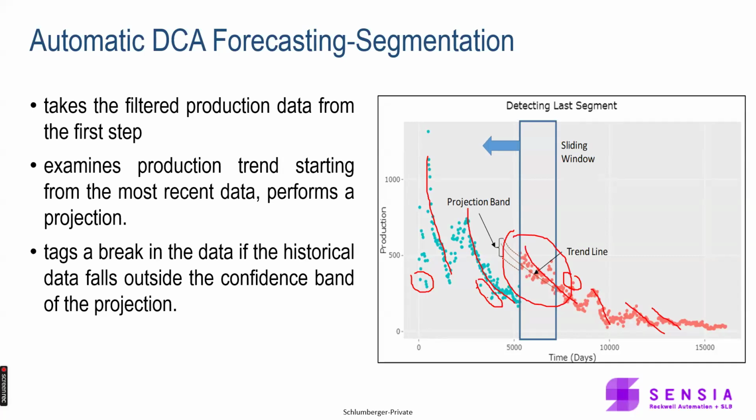So for example, maybe you are adding a gas lift and you want to apply a workover on top of the gas lift. So it will go to the time this well was started as a gas lift and follow the trend and clean the anomalies and outliers in auto mode. So it will do segmentation, trend analysis, and remove the outliers automatically, right? And then do Arps equations or regression for the Arps equation and find for you the decline and all the reserves and everything, right? So that's the state-of-the-art model in OFM for forecasting.